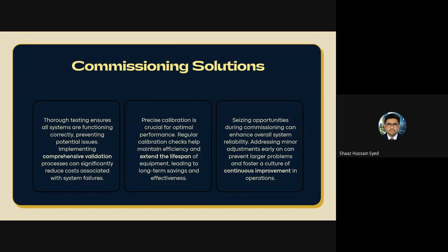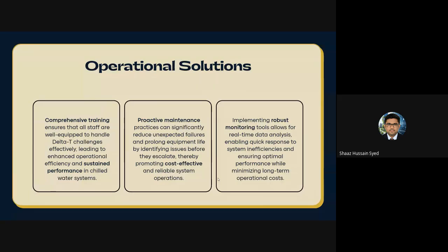And related to commissioning, we always recommend to flush the system properly, clean the strainers before testing and commissioning, balance coils one by one, tune valves and pumps, calibrate the sensors, and close temporary bypasses fully. That's how we usually recommend to clients to avoid a collapse in the delta T, or low delta T syndrome, for the buildings.